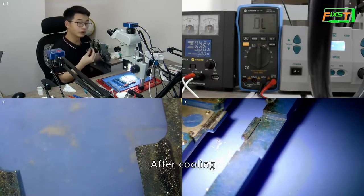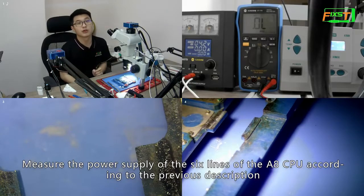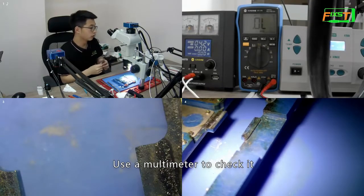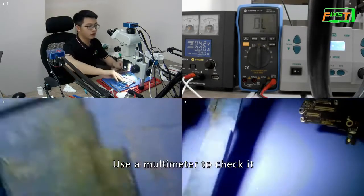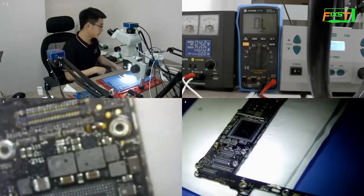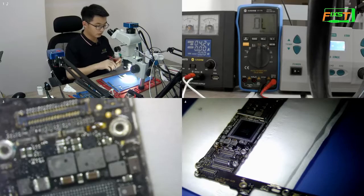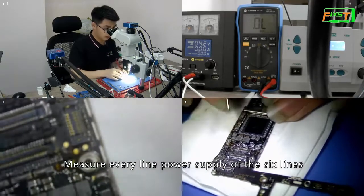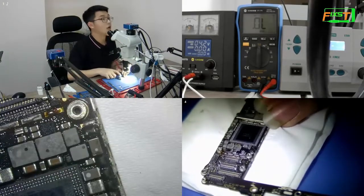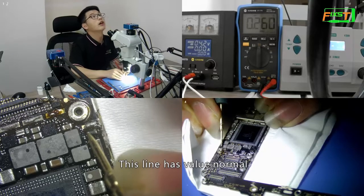After cooling, measure the power supply of the 6th line of the A8 CPU according to the previous description. Use a multimeter to check it. Measure every line power supply of the 6 lines. The first line. This line has value, normal.